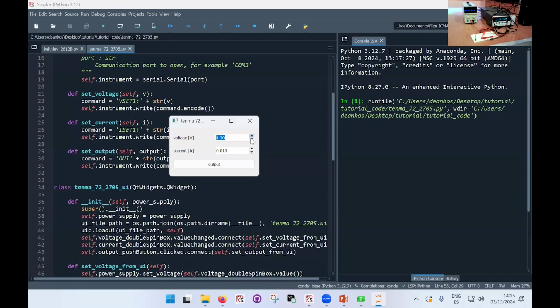But anyway, you see that something is actually happening in the power supply. And as well, I can change the current. So this is, for example, a current of 30 milliamps, and it's set to 1 volt. So I can hit the output, and now it turns on. You see this red LED that turns the output on and off. And if I now start to increase the voltage, you should be seeing this reading here, that's the current. Right now there is no current because I'm at a voltage that's not detectable. It's below a milliamp, the current itself, because we're in the off state of the diode. So it's below a milliamp and we're not reading anything.